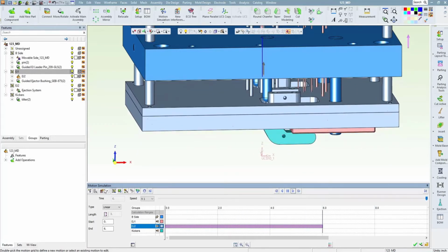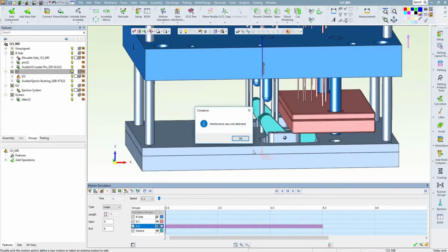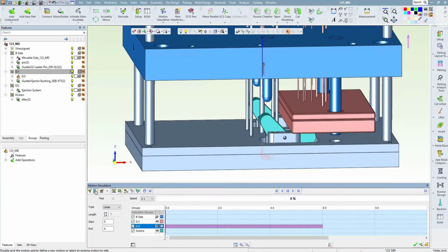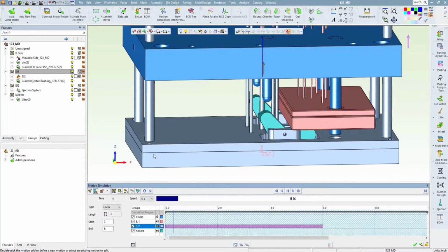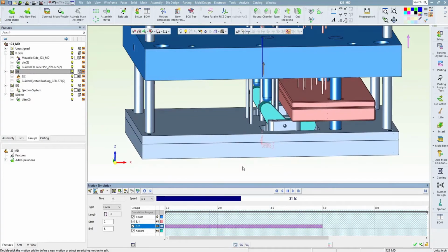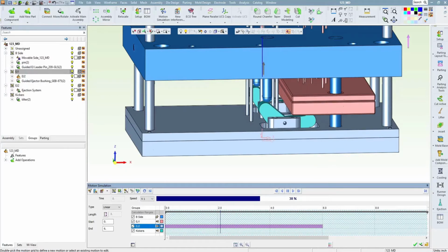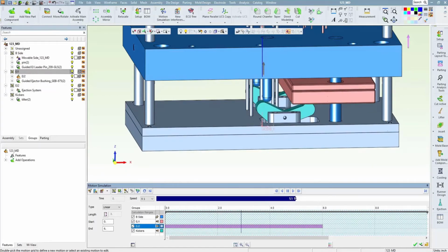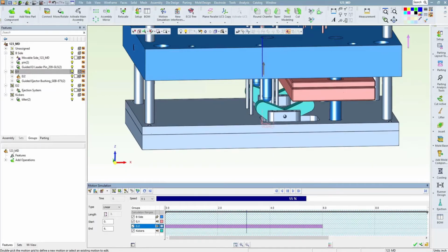The free test of the motion is what I expected, and the design has no current interference, so that's good. An example like this might be one that needs a permanent connection or two to keep the parts from slipping around, but having the pins and some guided ejection included in the groups will do the job of keeping all the parts in line. So there should be nowhere for the smaller ejector system to go but up.